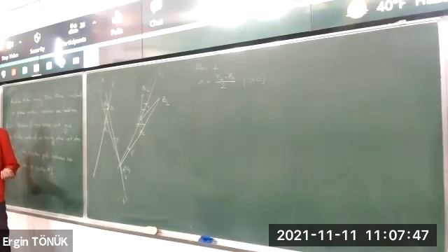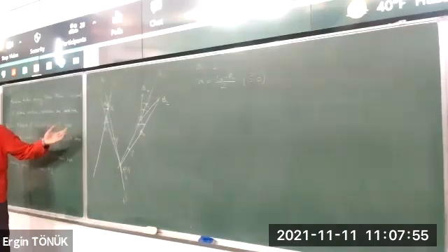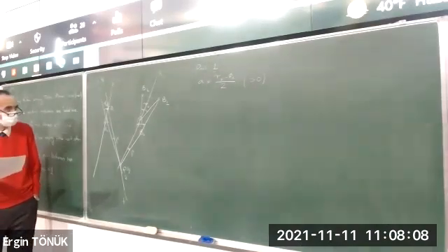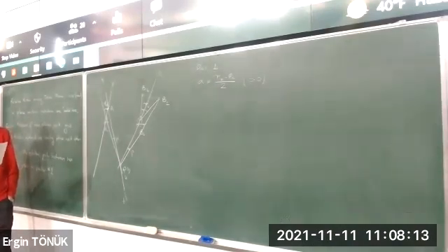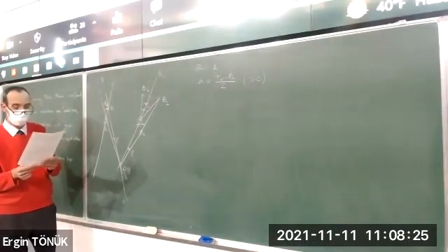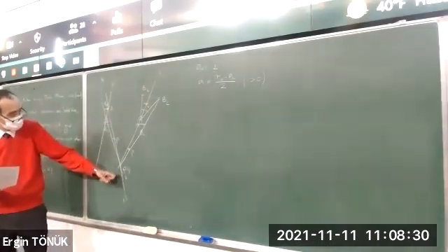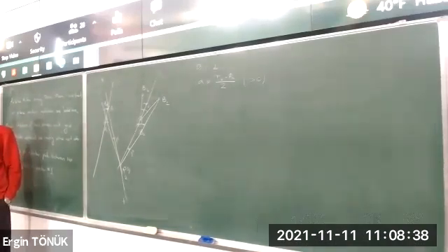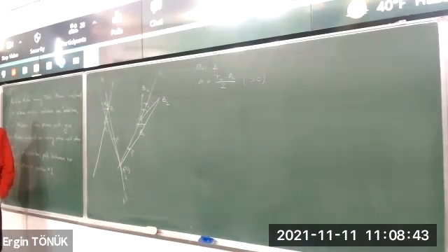So I have the 4 bar again. Of course, we still have the same trouble. The mechanism exists at the two positions, but the design procedure doesn't guarantee that the two positions are in the same branch, or the transmission angle is good, or the link factor ratios are good, etc. Now, in this procedure, we again have 3 parameters. One is we can change this length, therefore the location of D1, and also the initial angle, and we have arbitrarily selected R12. So 3 different parameters to improve the design. Okay, so this is like a recipe. You just follow it based on the principles we have seen up to now, and it's fully graphical.